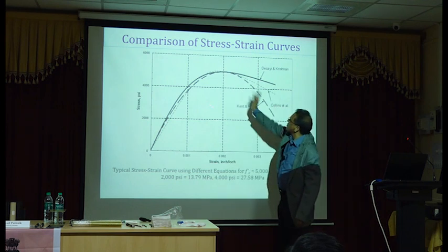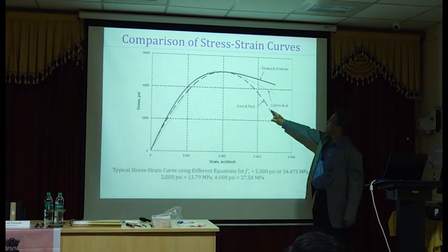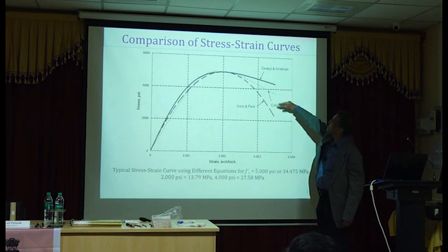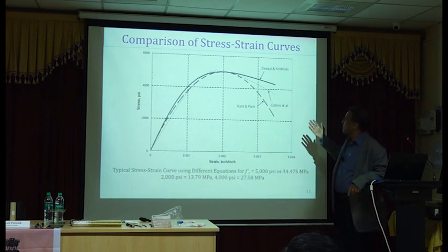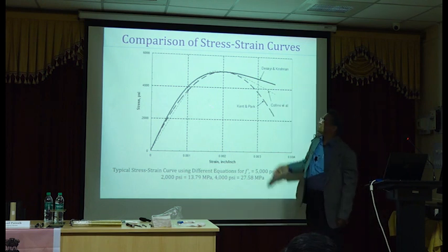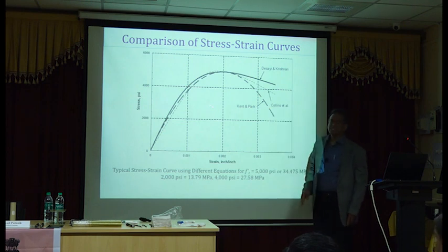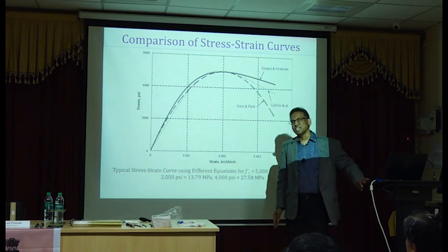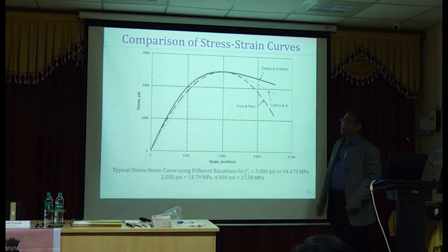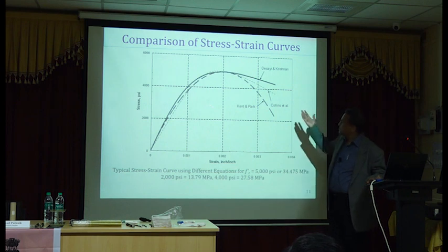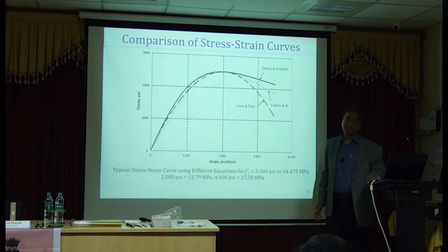Beyond the peak, the post peak, of course you have three different steepnesses here, but from my work I found out that these falling branches of these stress strain curves are not making much difference in the final analysis. Okay? You may find a different conclusion, but that's from what we did. In most cases we did not find much difference, maybe 1 or 2%, maybe maximum 3%.